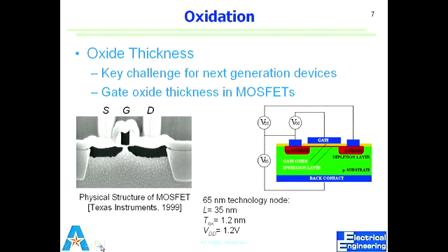But generally it's the half pitch, or how often can you repeat two lines, interconnect, right? But it can be any smallest feature that we can make. That is what is defined as the node, 65 nanometer or 45 nanometer or 22 nanometer.